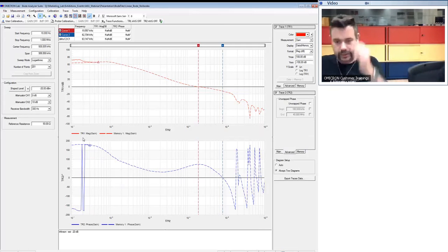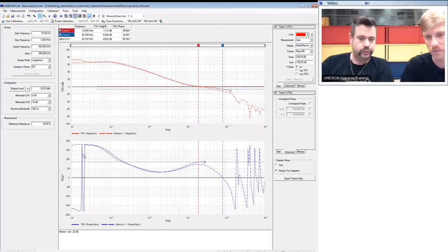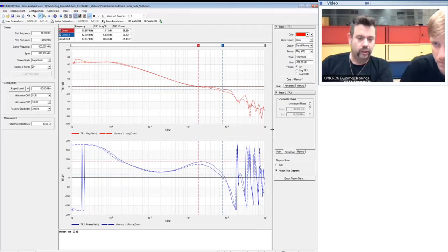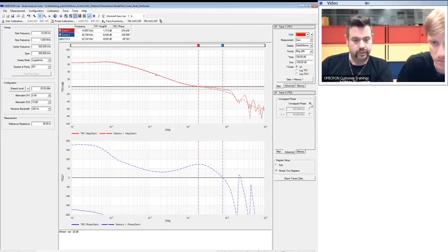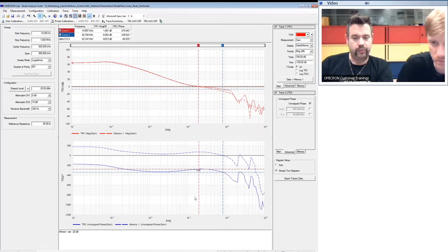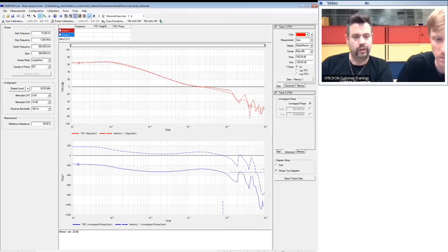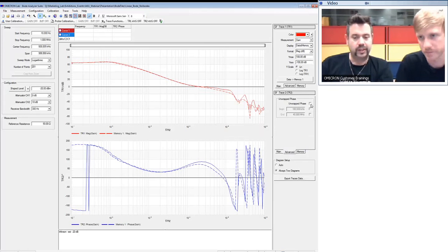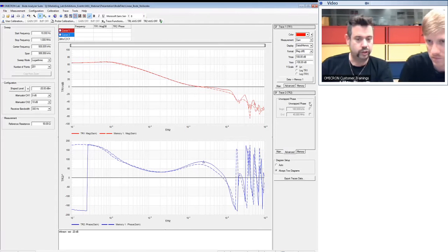Yes, we can use this phase unwrap function. The only problem is we need to put the reference point right at the beginning. If you activate it, you see that immediately your phase jumps and it starts at minus 180 degrees, and now your phase is shifted. Now you need to find out what is the point where the phase is crossing the 0 degree line, or where to reference to assess the phase margin. Therefore, in this case, we do not recommend using this function.